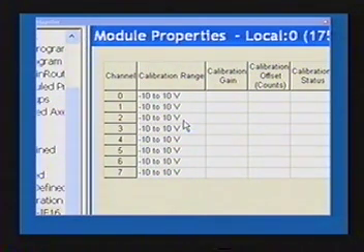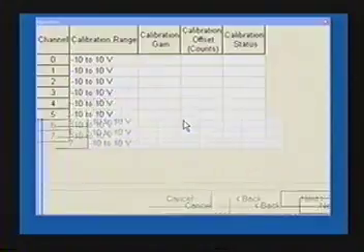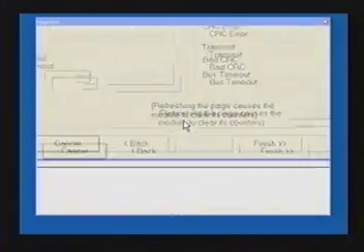I noticed that the equipment that we had in our facility was not high enough. The resolution was not high enough to make this work. So stay out of the calibration mode. Just leave it alone. If your card doesn't work properly, send it back to Allen Bradley. They'll send you a new one, and it'll be recalibrated. So you don't have to worry about this. I strongly recommend, unless you're a calibration lab, you need to stay out of this section, out of this area. So, and that's it. You're finished.